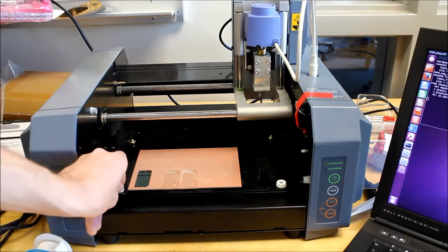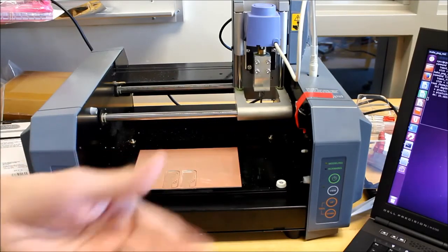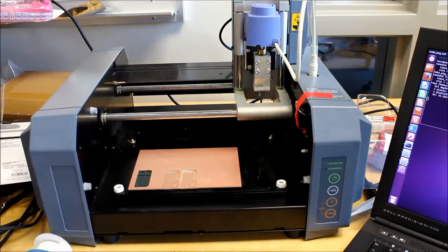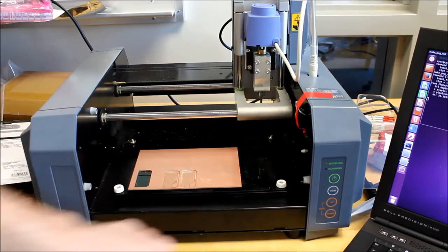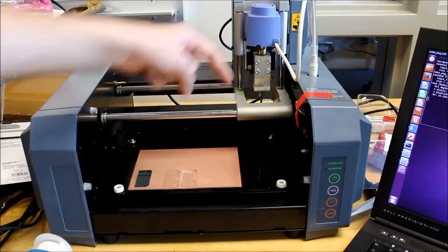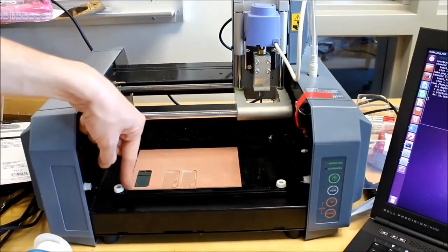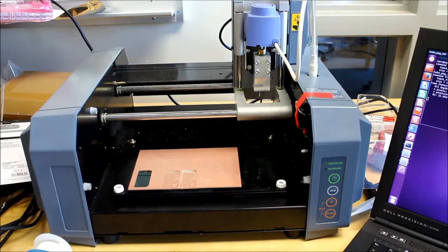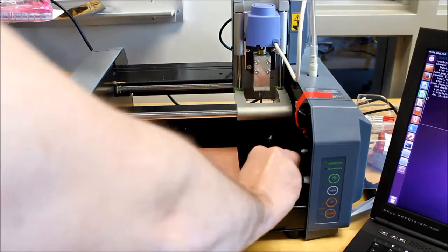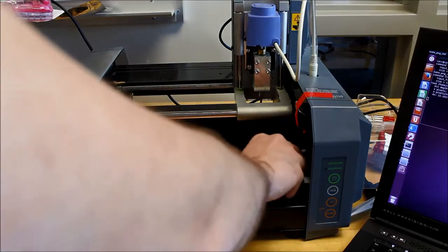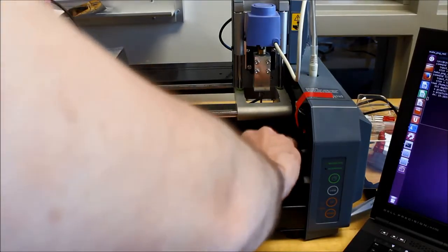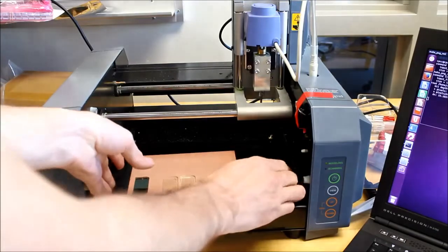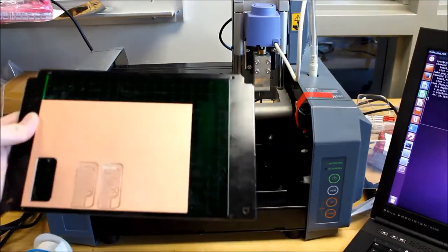Something that's important about this machine is that you can't actually send files to it or commands to it when it's in view mode. In order to send data to it, you have to push the view button again, and then the spindle will come down here to X0, Y0, which is the origin. And now I'm going to show you the plate that is removable. So you unscrew the two white screws at the bottom, and the top plate removes.